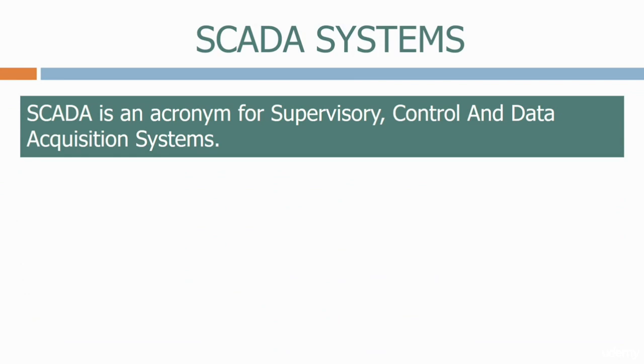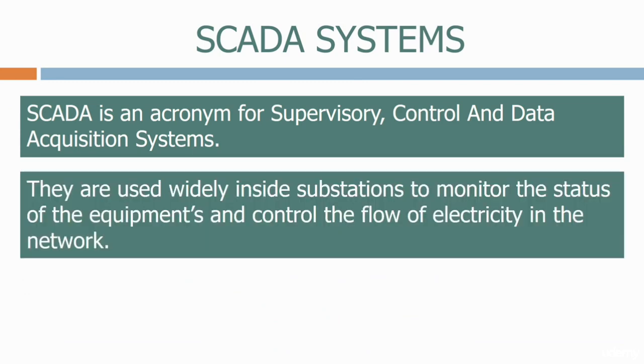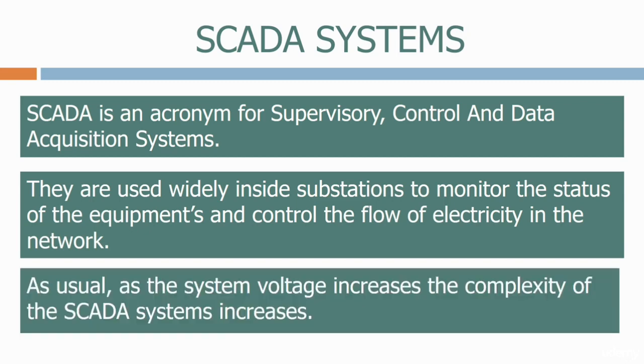SCADA is an acronym for Supervisory, Control and Data Acquisition Systems. They are used widely inside substations to monitor the status of the equipment and control the flow of electricity in the network. As usual, as the system voltage increases, the complexity of the SCADA system increases.